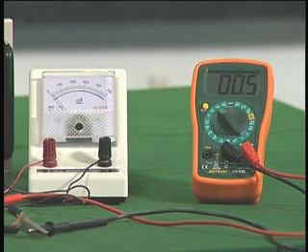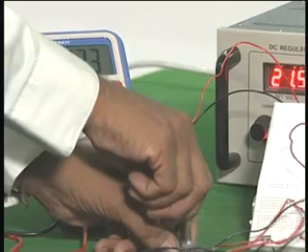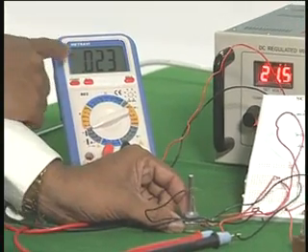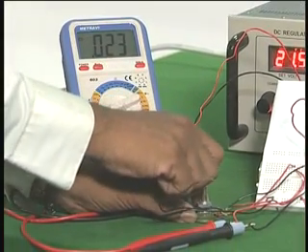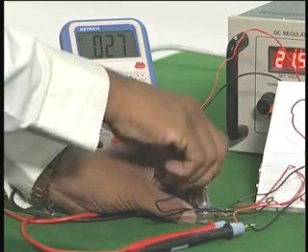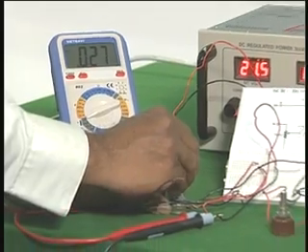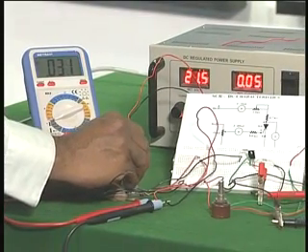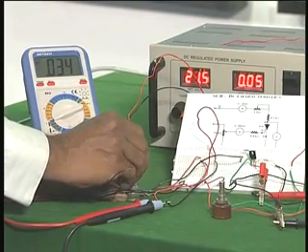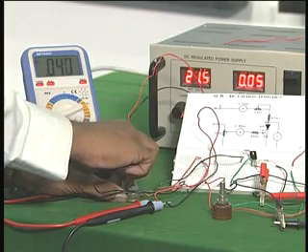So if I want to bring the SCR into off state, the only way I can do is by increasing the resistance in the circuit. Therefore another potentiometer I am going to vary. Now I want you to look at this current here. Now the current is decreasing, because I am increasing the 1 megohm resistor in the circuit. So when it comes to a very low value, then suddenly you will find it will become 0, that means the SCR has come into off state.